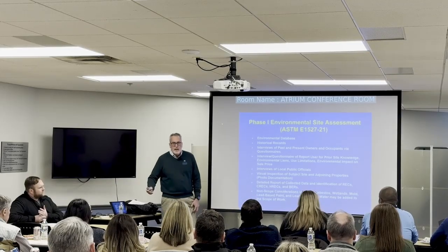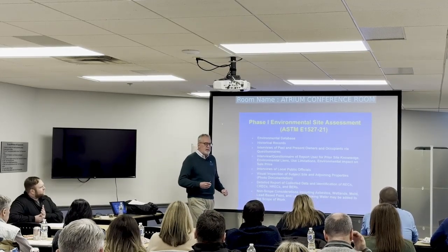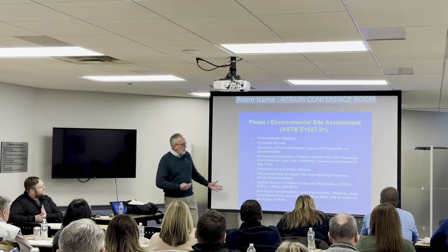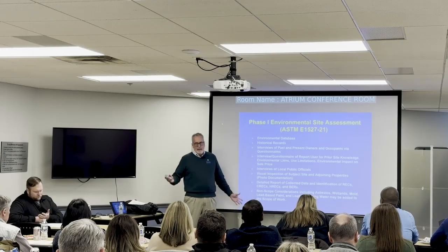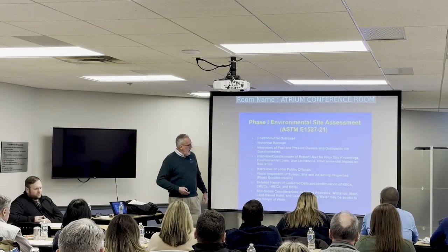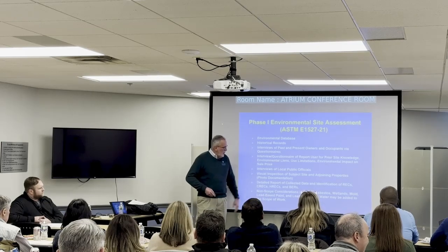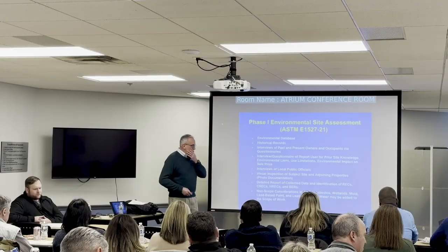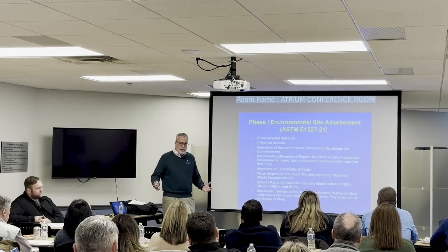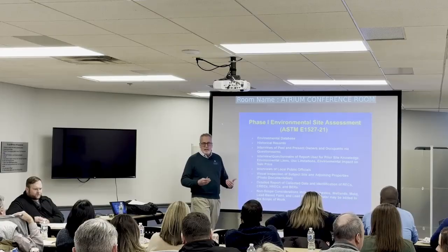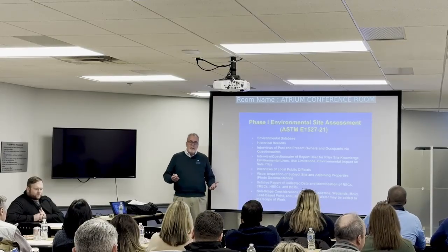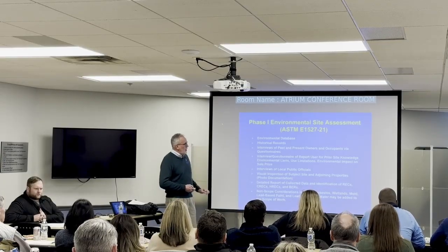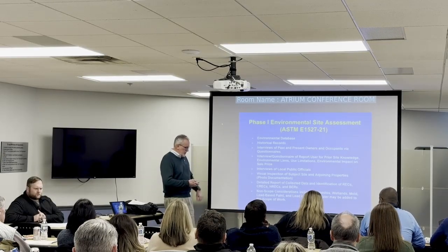And when we do a project that's a new development site, that's first developed, it's farmland, it's got some woods, it's got a creek that runs through it, we certainly say, hey, you might want to take a look at wetlands because that can have a significant impact on the use of the property. As well as SBA has requirements for child care facilities, requires lead-based paint, lead and drinking water testing. Asbestos, if you're going to do some significant renovation or demolition on a building that was constructed, say, prior to 1980s, you might want to do an asbestos survey. So non-scope considerations can be added to a phase one, but just want to be clear on what a phase one environmental site assessment is.